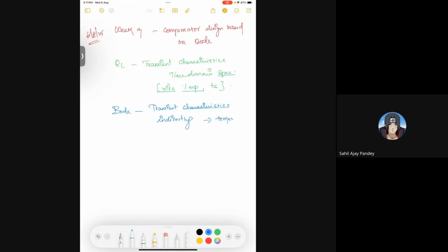The ultimate aim is to make the system meet the specifications, but there are different methods of solving the problems, different viewpoints, maybe from time domain, that is a direct method. Now we are going to use the frequency response method, which is easy to design, but the parameters are being explained indirectly here. That is the only main difference between these two. So when you see the frequency response plot, that indicates clearly in which system it should be modified or how it should be modified, although the exact quantitative predictions of the transient responses cannot be made.